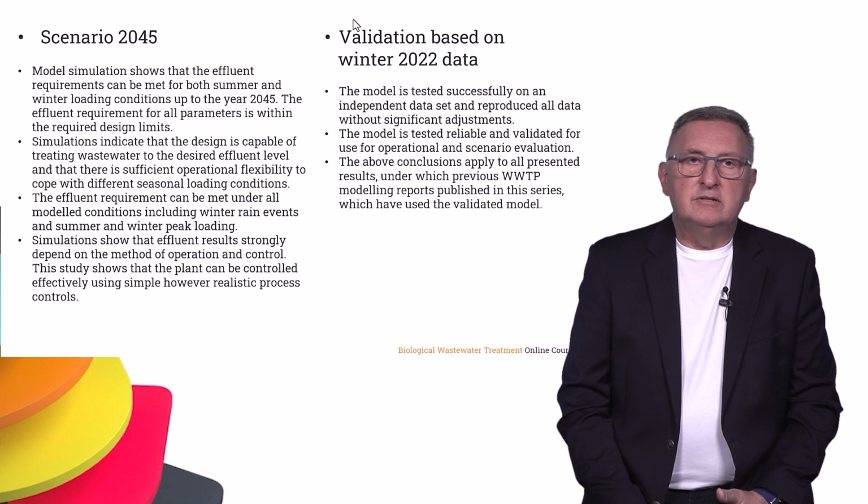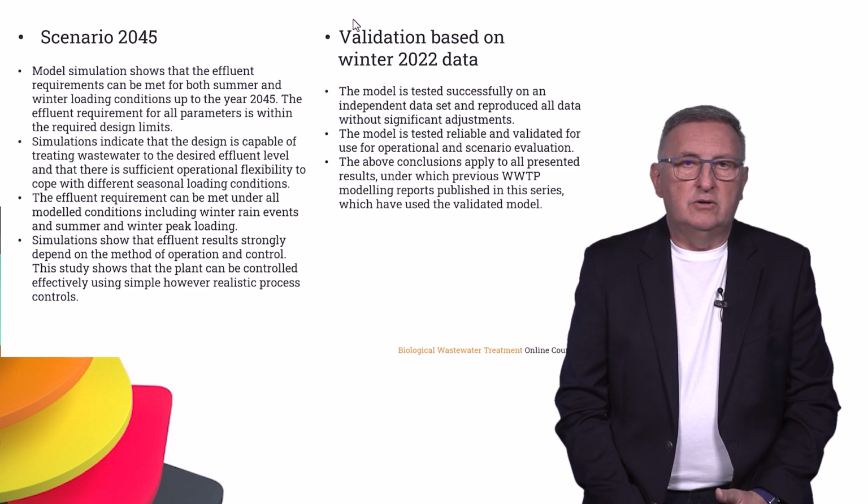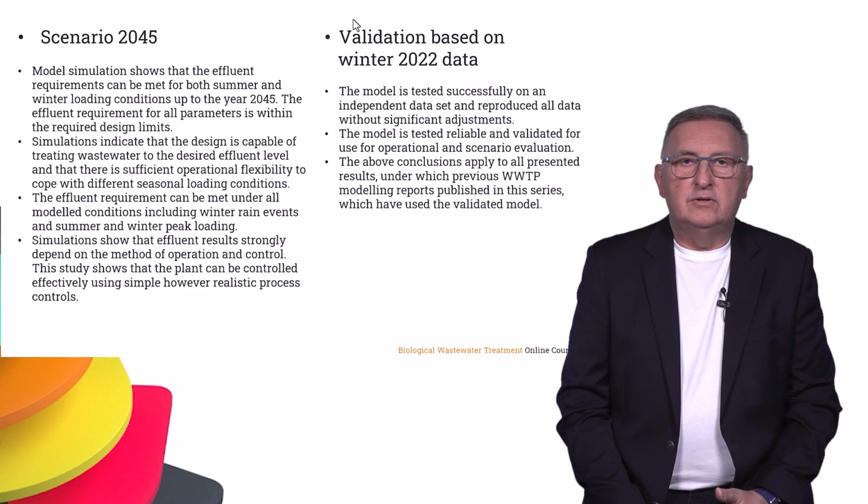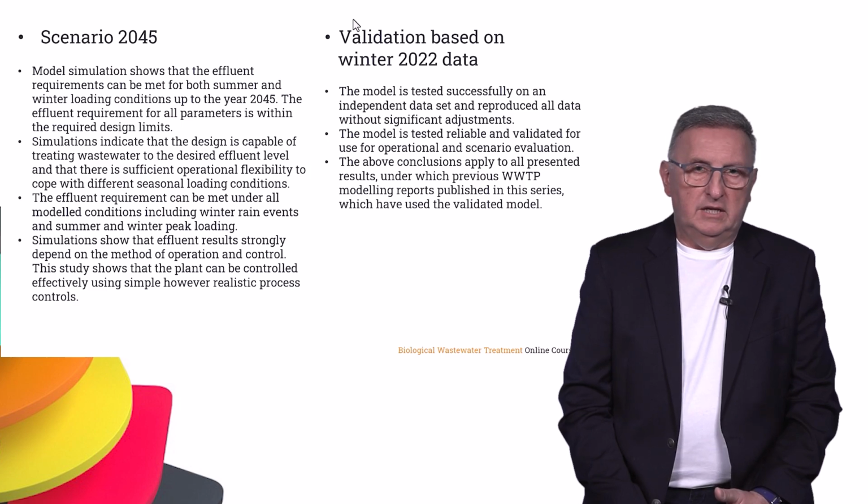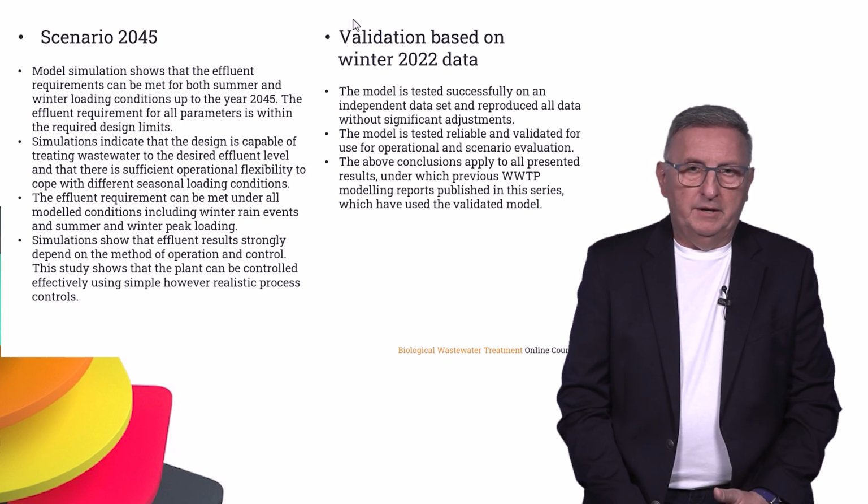The scenario 2045 was based on the calibrated model and showed, what is also important, that all 4 wastewater treatment plants will be able to deal with the incoming pollution in that year of our design horizon. So treatment plants are expected to operate efficiently also in coming years when the flow and load will increase.